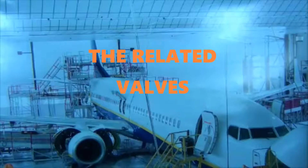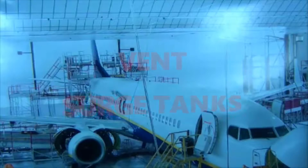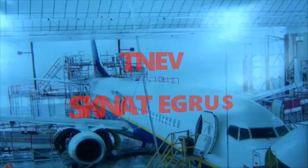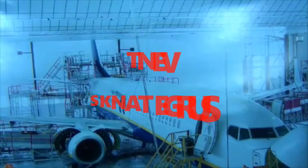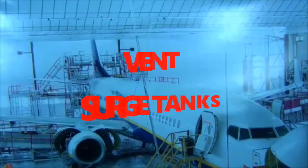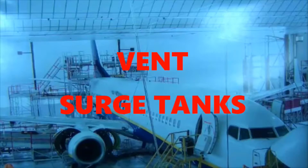And then you also have these surge tanks. Remember I said that you have the vent tanks at the outer edge of the wings. Okay, so those vent surge tanks are going to keep that fuel tank open to the external air pressure. Okay, so remember what I said, pressure is very important, and it's constantly changing. All right, because you don't want a really large disparity. You don't want your differential pressure to be too much, because then you're going to cause damage to the aircraft. So it's just physics is physics, guys.